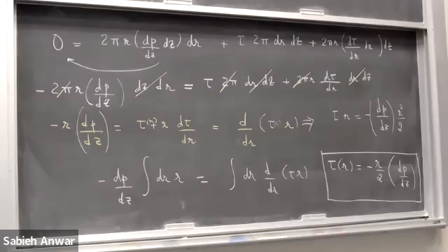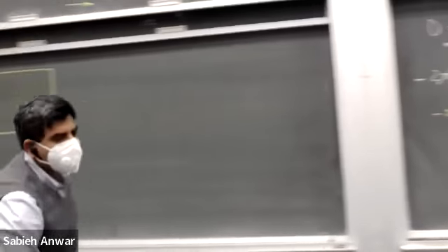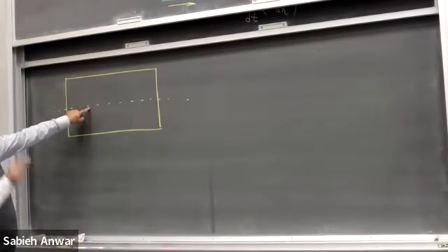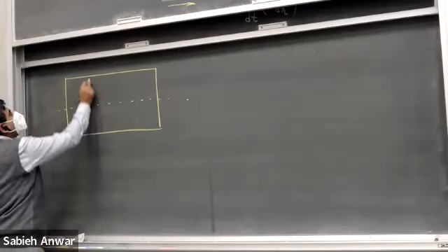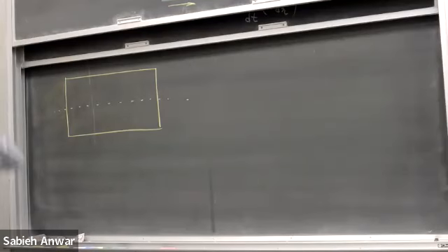So this is a longitudinal section of my pipe. This is my central axis. What that particular equation is showing is that the shear stress tau is not constant along this section. It's variable. It depends upon how far you are from the central axis.